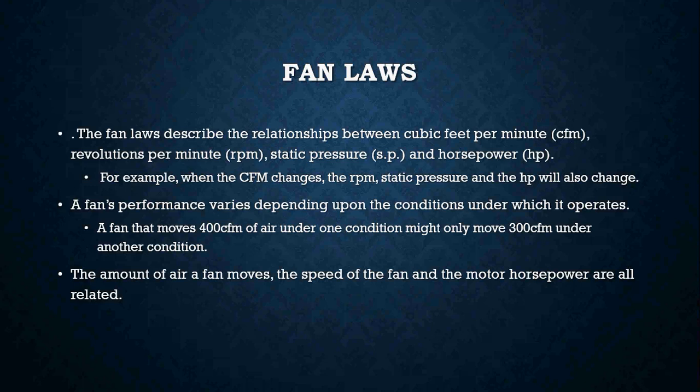Those fan laws make us understand that what we do to a fan is going to affect airflow performance. So if a fan isn't operating at the correct RPMs, it's going to affect its ability to give us the correct amount of CFMs.